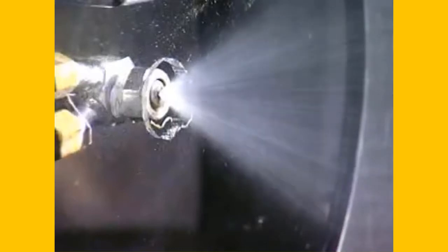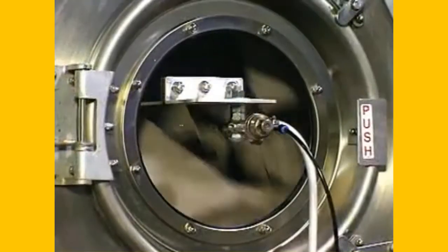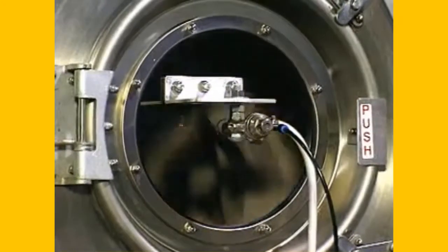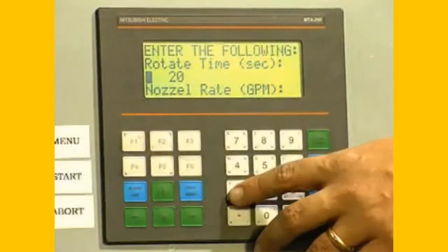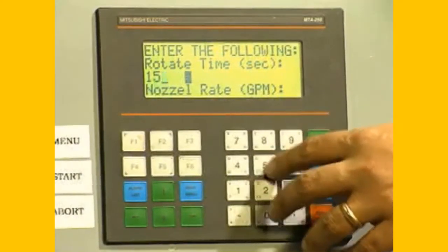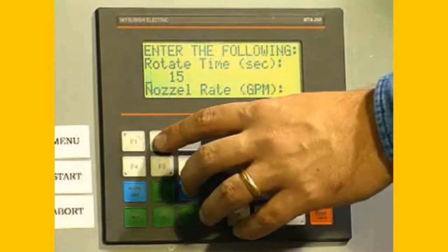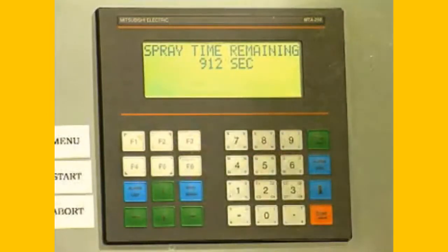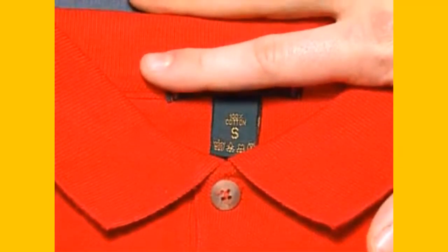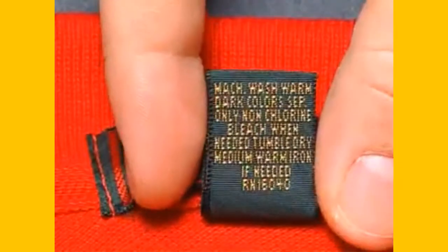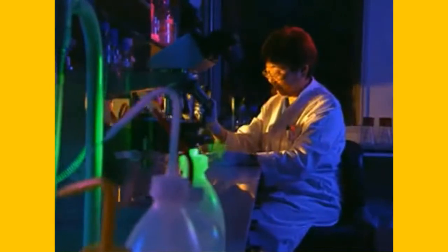A second method associated with garment resin applications is metered addition. With this approach, cut and sewn garments are sprayed while tumbling in a garment machine. There is much less waste in chemicals because a metered or measured amount of water and chemistry, just what is needed, is sprayed on the garment. You've seen many different ways that fabrics or garments can be treated with chemicals to improve wash and wear and wrinkle resistance. There is yet another way to soften and improve the appearance of fabric that is becoming more important.